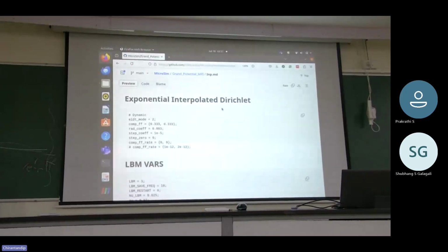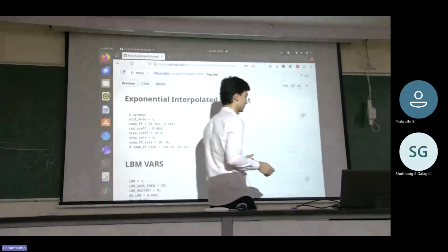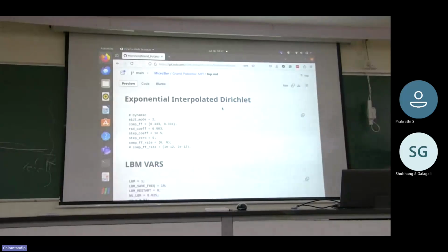situations that you know these experiments also mention, right? Because of this, what you can now start to do is, let's say, in your phase diagram, there are a variety of far-field compositions where you get couple growth or some type of microstructure formation. And in experiments, typically you will do one experiment to figure out what the microstructures are, right? But in a simulation strategy, what you can think of doing is to span all of those compositions in one single run.